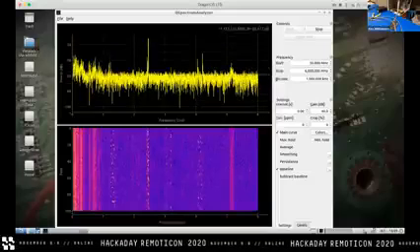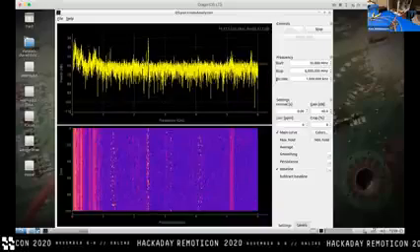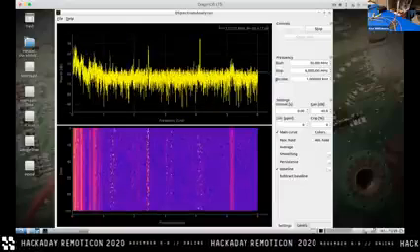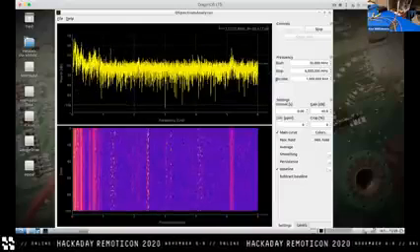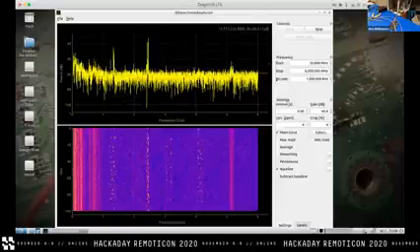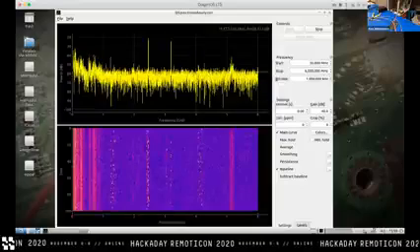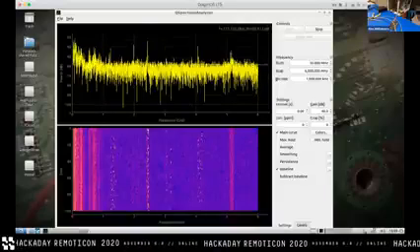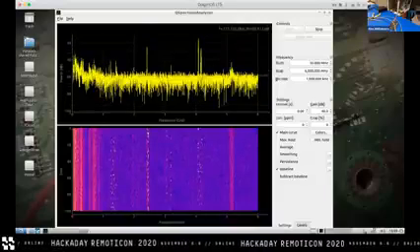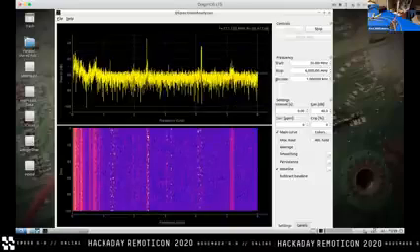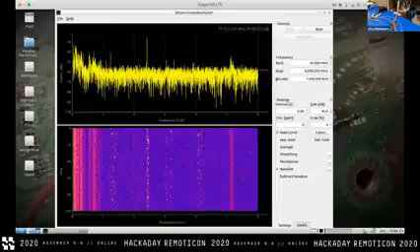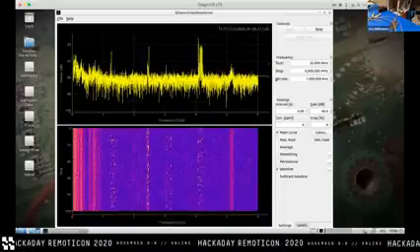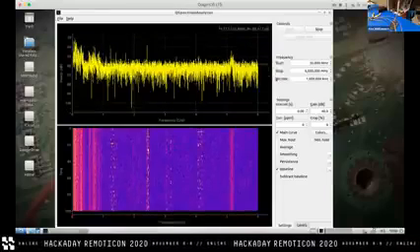Yeah, one thing that strikes me as true this day and age in engineering, especially with RF stuff like this, is stuff just doesn't cost that much to build anymore. So if you want serious gear that does a good job, that will cost you money. Like this Tek RSA, its real claim to fame is that its offset is basically negligible and very well calibrated when you move from one chunk of spectrum to the next, which is definitely not true of the SDR stuff. You notice that the noise floor of the HackRF doesn't look like it drifts around as it scans, so it's pretty good.